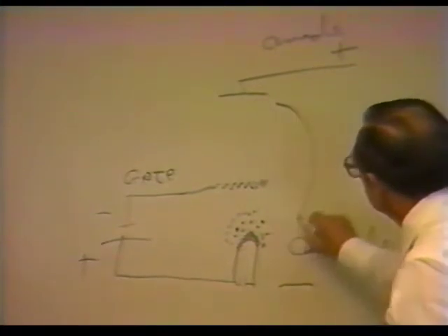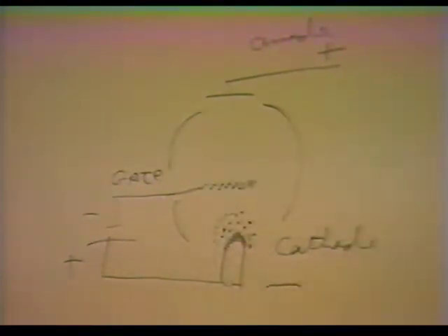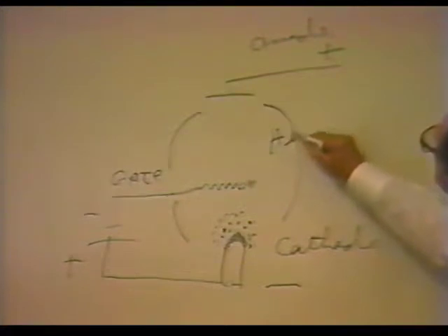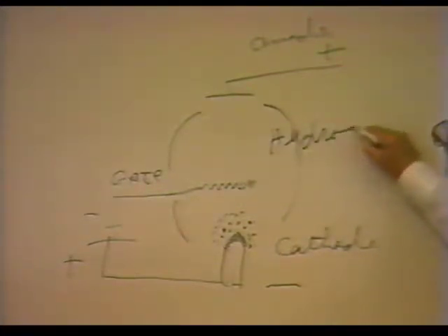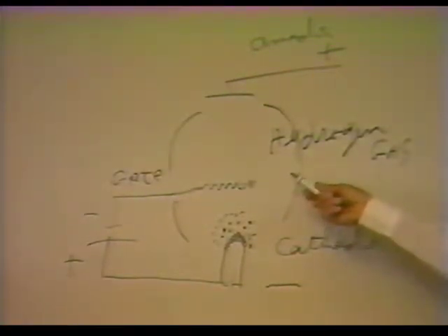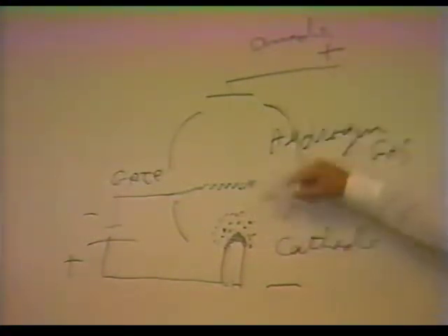Now, since this was a hydrogen thyratron, we put a glass envelope around it and we put a gas inside of it. And we put hydrogen, however you spell it. Now, hydrogen gas served the purpose later on of providing a very low conducting path. Now, the pressure of this hydrogen gas inside the envelope was critical and was determined by how much voltage you wanted to hold off.